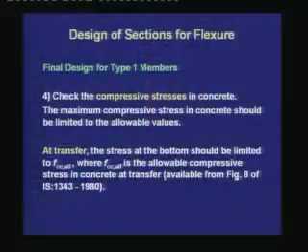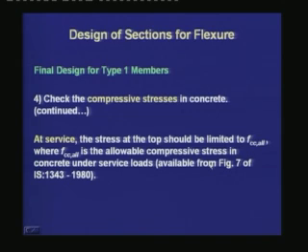The fourth step is to check the compressive stress in concrete. The maximum compressive stress in concrete should be limited to the allowable values. At transfer, the stress at the bottom should be limited to FCC allowable, where FCC allowable is the allowable compressive stress at transfer, and this is available from figure 8 of IS 1343/1980. At service, the stress at the top should be limited to FCC allowable, where FCC allowable is the allowable compressive stress in concrete under service loads, which is available from figure 7 of IS 1343/1980.